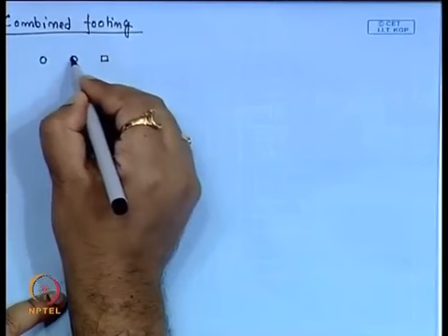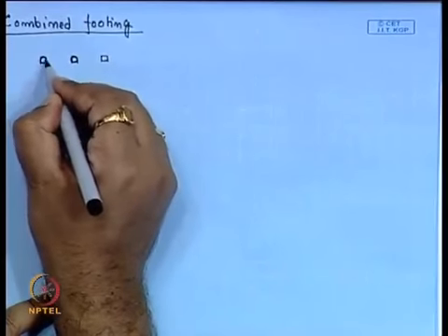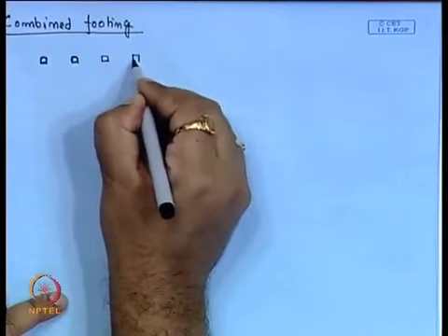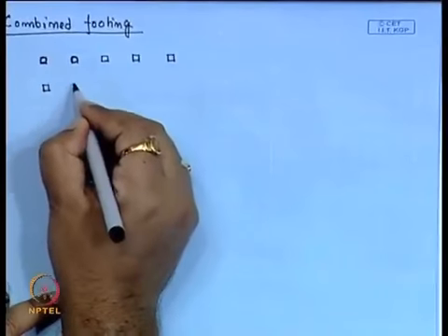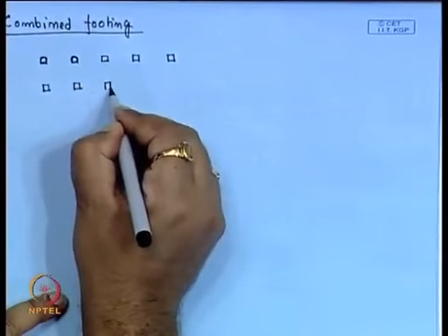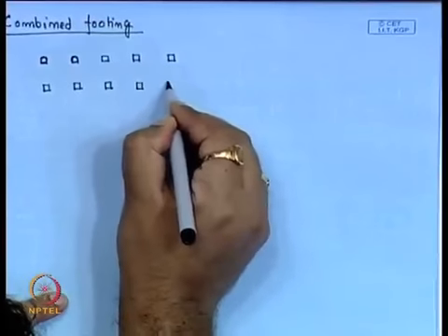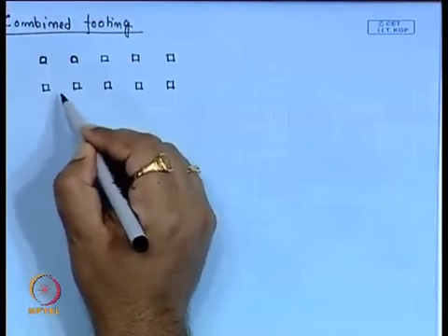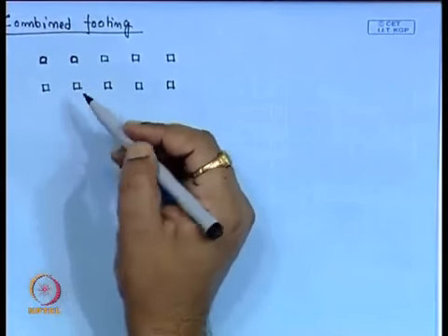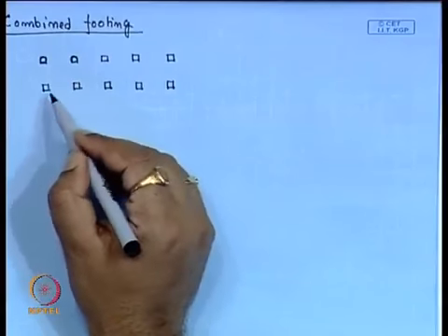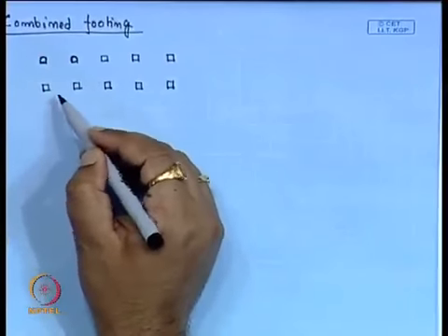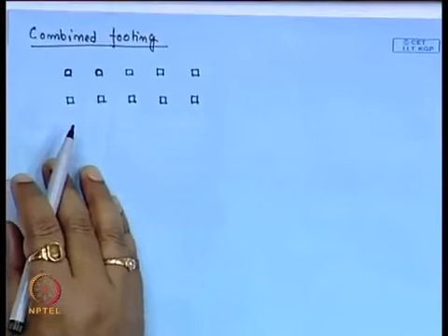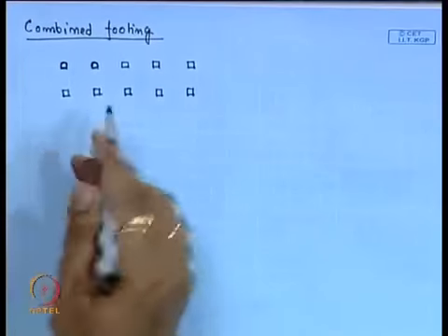So, these are the columns. Now, if we want to design isolated footings and the spacing between these columns is very small, then it is obvious the influence zones of each column will overlap. So, there is a chance of an overstress zone.